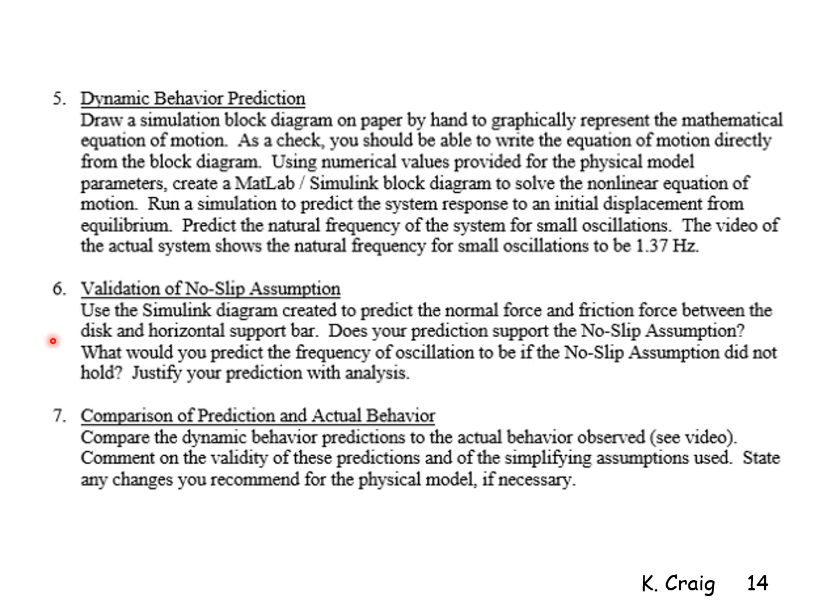However, if that's not the case, then I need to revisit my analysis and relax the no-slip assumption, in which case the rotational motion of the disk is not related to the translational motion of the disk. I have a 2-degree of freedom system. I need a coordinate x to describe the translation of the disk, and an angle theta to describe the rotational motion of the disk. The no-slip condition would not hold.